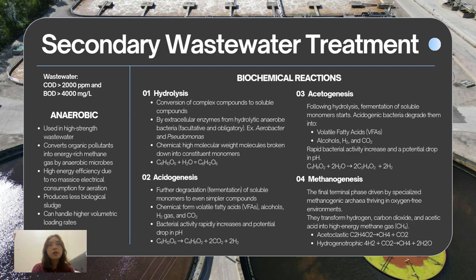The fourth reaction is called methanogenesis. It is the final terminal phase driven by specialized methanogenic archaea thriving in oxygen-free environments. They transform hydrogen, carbon dioxide, and acetic acid into high-energy methane gas. The first pathway is acetoclastic methanogenesis. This means acetic acid is broken down into methane gas and carbon dioxide. This pathway contributes around 60 to 70% of methane production.